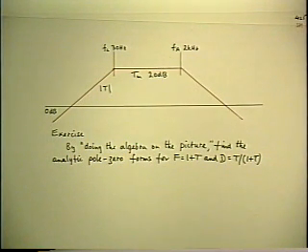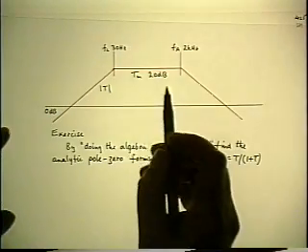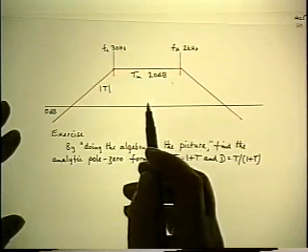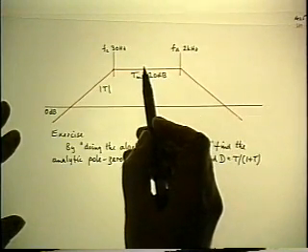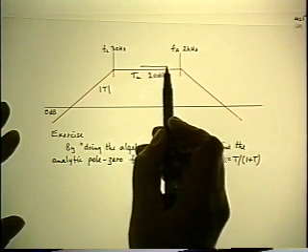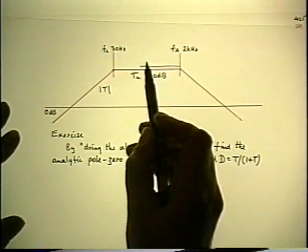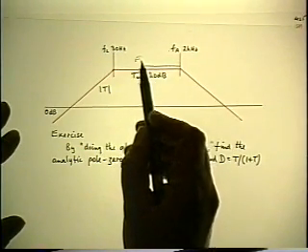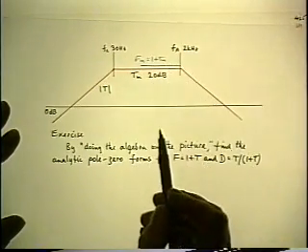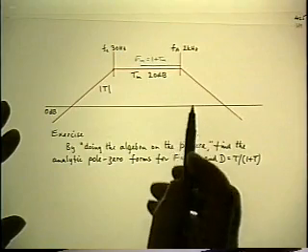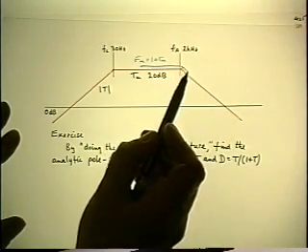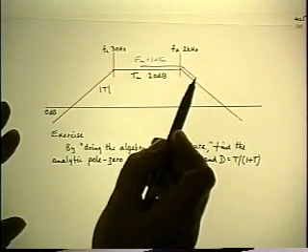Well, I'll go ahead with the construction now. Starting with the mid-band value, always the most important, of course, in this case. F is 1 plus T, so it'll just be a little bit bigger than the Tm. So this is Fm equals 1 plus Tm. When you get to the pole of T, the F is going to turn around at the same pole and is going to follow the same slope.